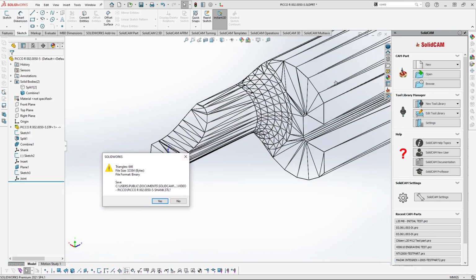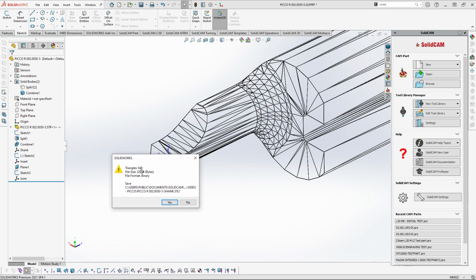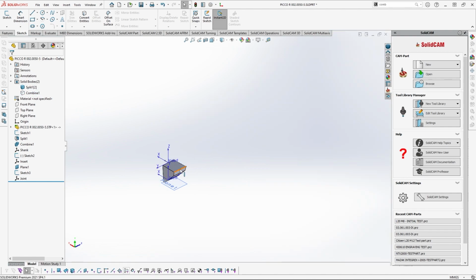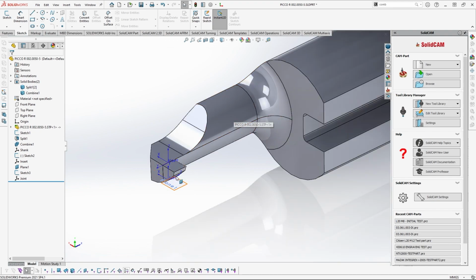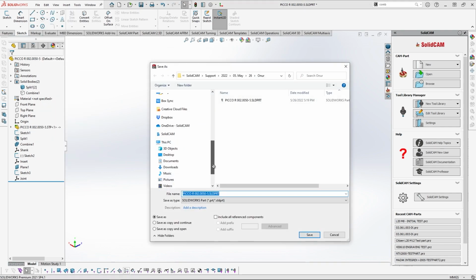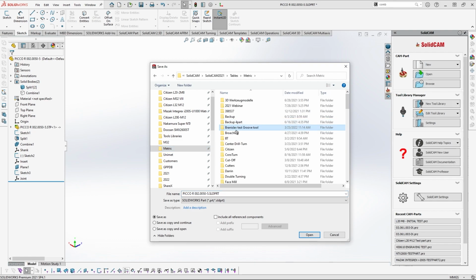Here it is. You can get the rough idea of the STL's resolution that will be generated. If you don't like it, or if you like a different resolution, you can also change the tolerances in the export settings. Right, now I'm going to hide this, and you can also hide it with the tab key and hide it with Control Shift. And so I'll hide this one, and now we are going to export the insert,